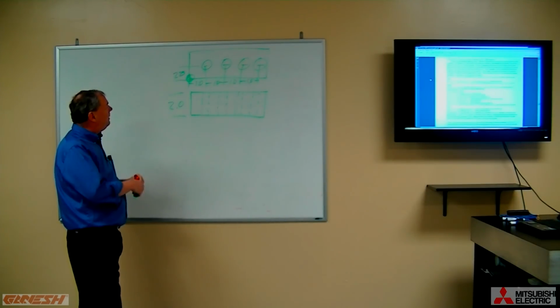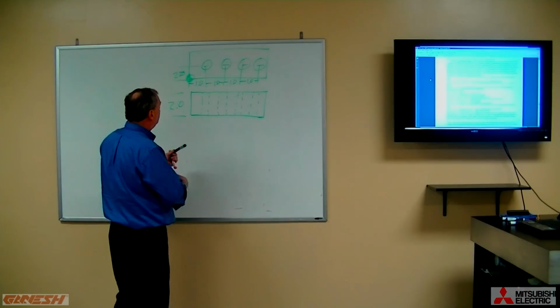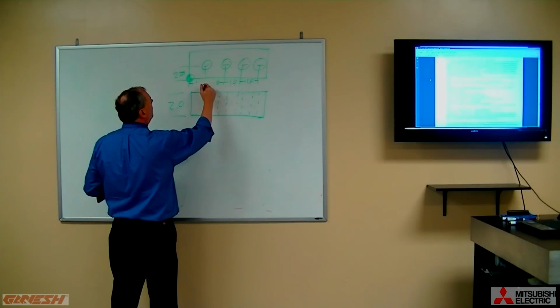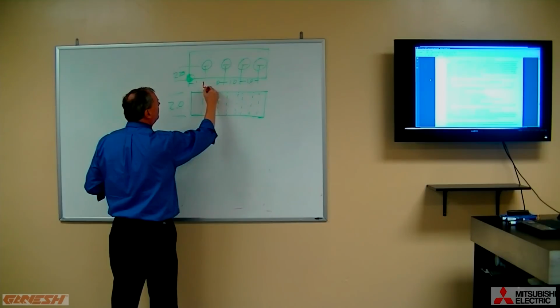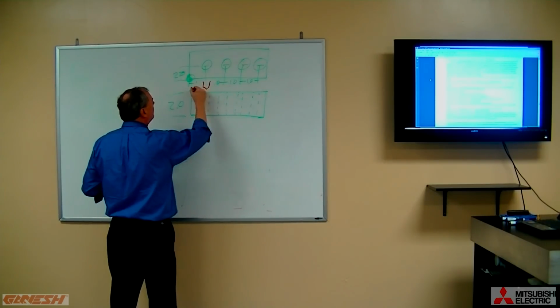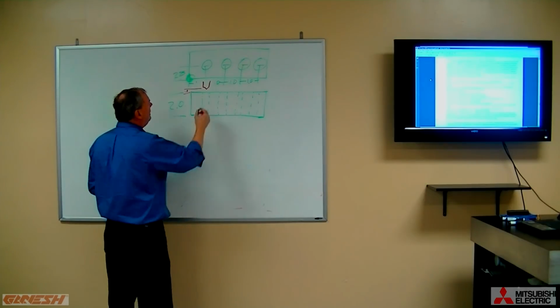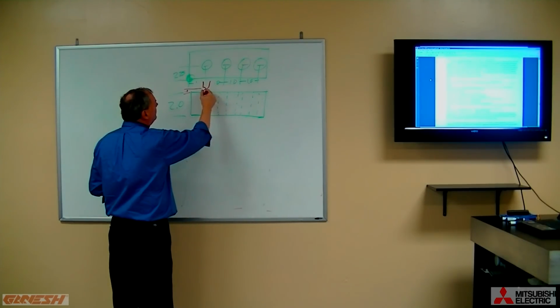Now the movement you want to take is we want to establish an R-plane slightly above the part, so I like to use the number 0.1, that's about 1/8 of an inch. And then each time we go down, we want to take 0.2 of material before we pull back out again.